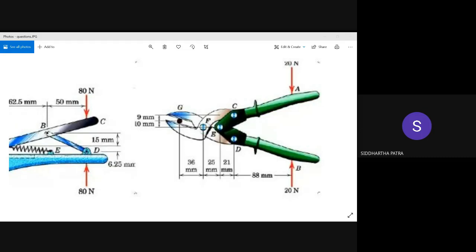If I take moment about F, then I know one relation among the two forces that are at C. So I'll get one equation for Cx and Cy if I take the moment with respect to F. Next, if I move on to the member ECA and again take moment with respect to E, this time I'll get a second equation involving the components Cx and Cy.